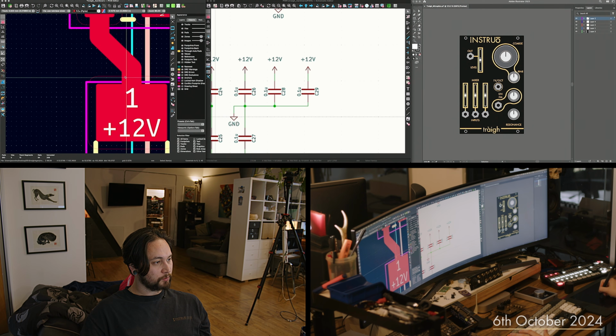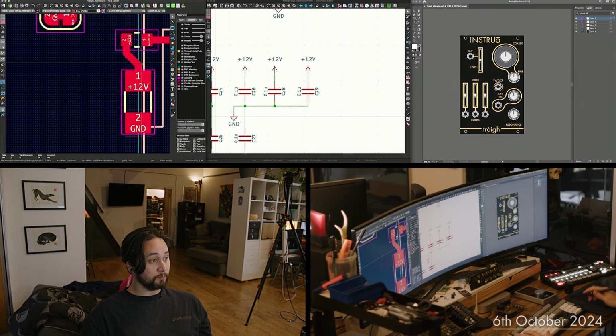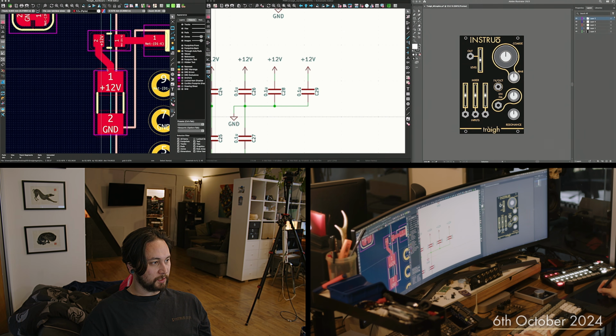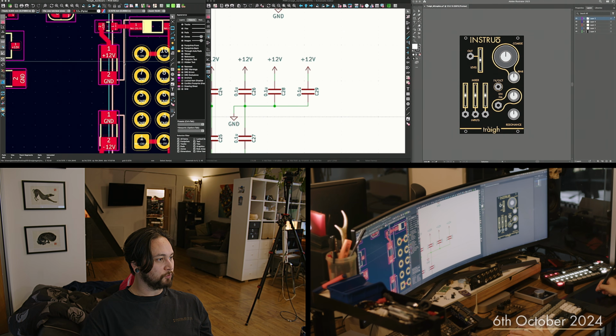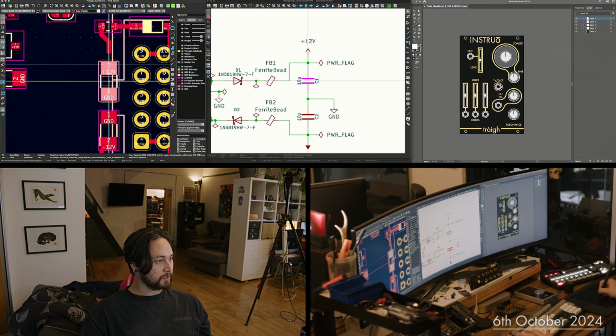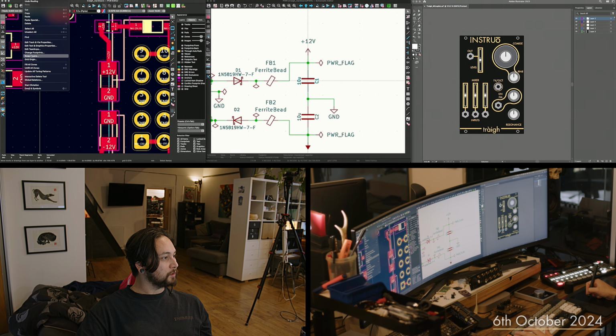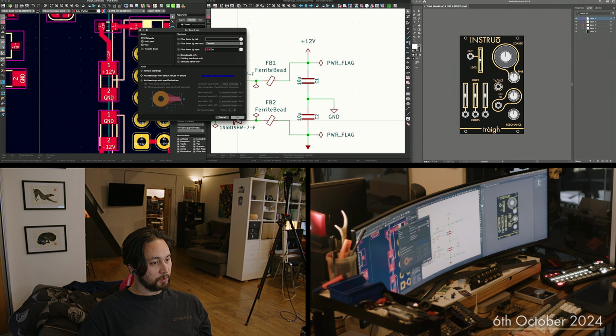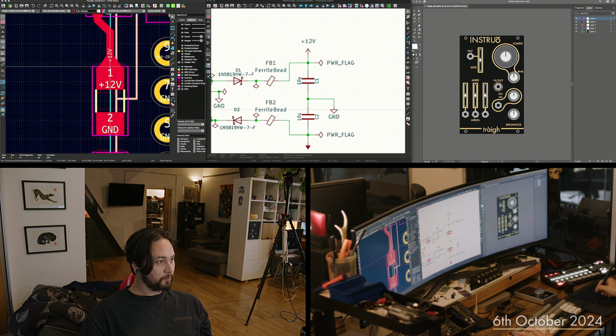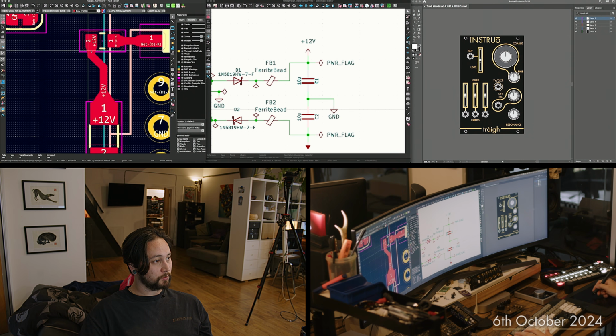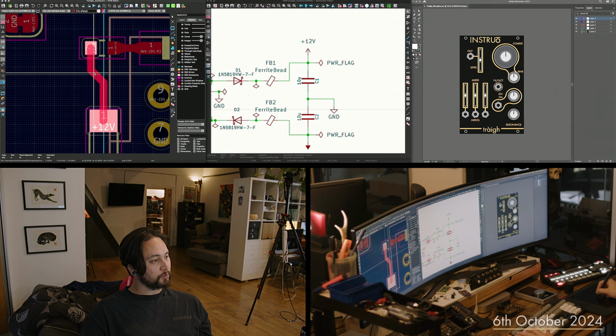Like with reworking, that's where traces can break or lift, because as that heats there's a lot of strain put on that, because it's a right angle and that's a thin weak point. Whereas if that was teardropped, let's say I moved this, test proof of concept, do that, teardrops, apply. There, that's much stronger now on either end there. I might even pull that down.